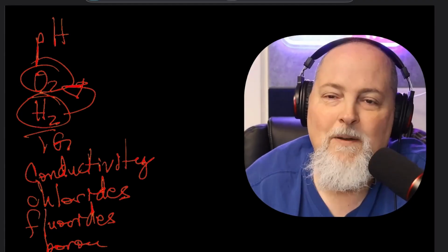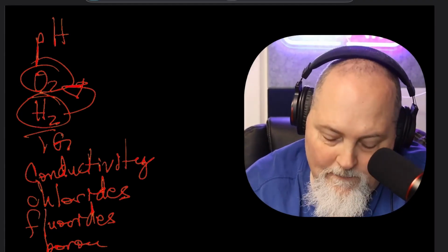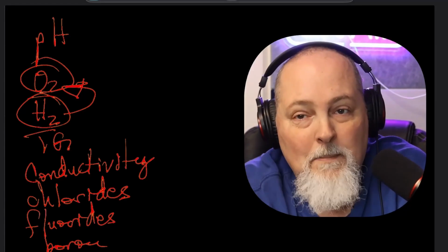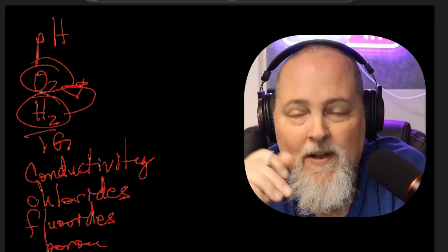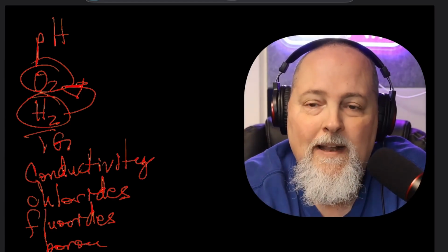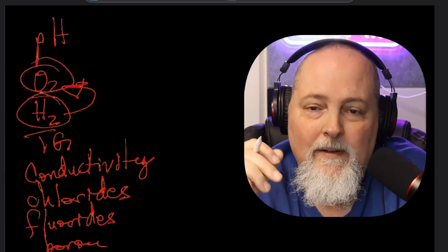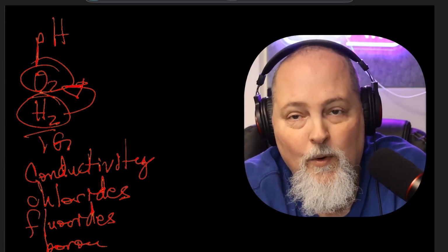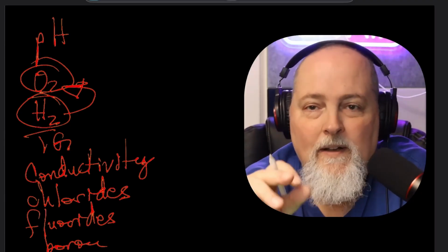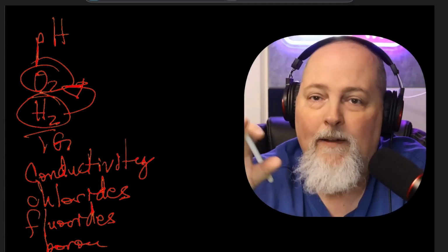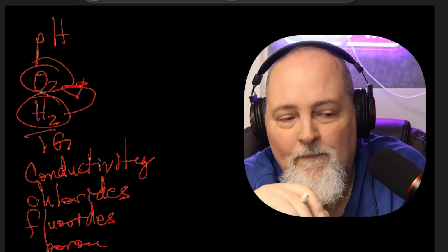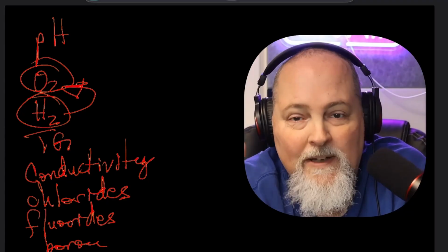Total gas matters because dissolved gases come out of solution and form gas pockets. Those gas pockets build up in the pumps. We have pumps in both PWRs and BWRs, and these gas pockets will collect and damage the pumps. It leads to erosion, which creates corrosion products, which can get activated, cavitation, loss. Conductivity is a measure of that. If we start damaging a pump and those products go through the coolant, then conductivity goes up, and it's a useful indicator.